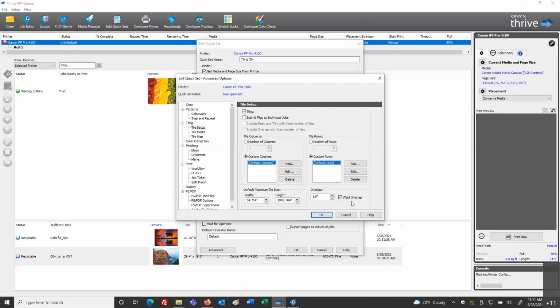And that could be if you're having some type of restriction where putting the two media tile panels overlapping and lining them up and then adhering them or heat welding them, somewhere to the effect where the ink on the media is interfering with that process of adhering, we can make this weld overlap active, which will make a portion of that non-printing, and therefore it's media to media, and that could help us in the cases where the ink is causing some type of area where it won't want to stick too well. Okay, so that's just the optional settings.